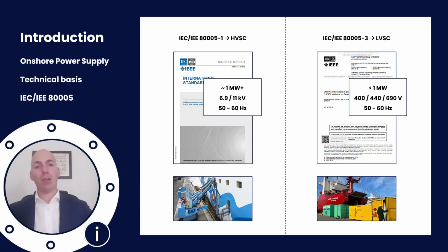I've got to say, I've done both, quite a few. Currently we mostly focus on high voltage systems because these are bigger ships that are targeted by more regulations. With lower voltage systems, in fact, sometimes if you have 400 or 440 volts, you can actually get away with available industrial sockets, plugs, or solutions that are at the terminal side already.